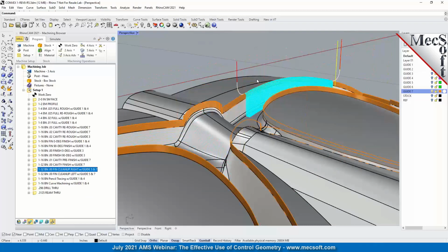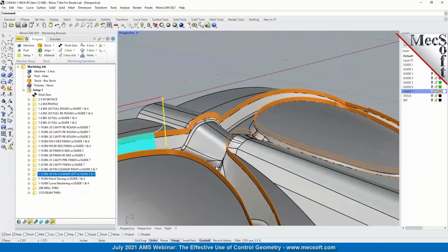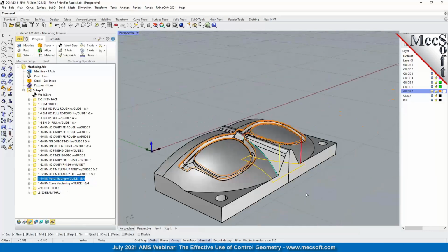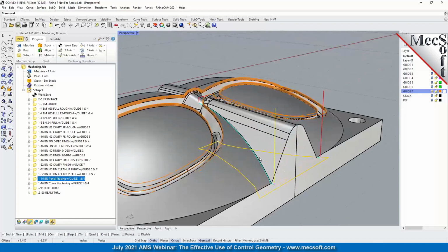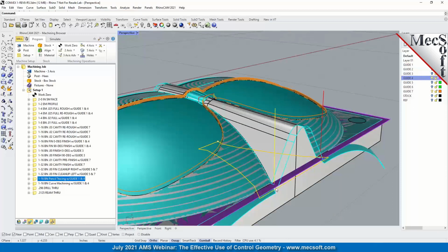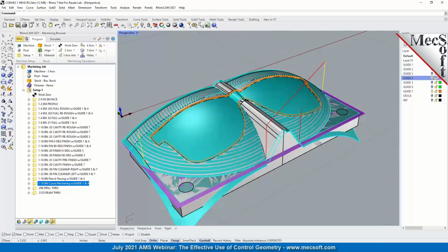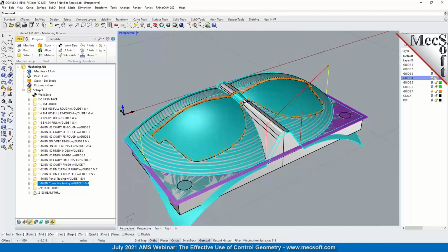And then move on past, we got extra cleanup there, extra cleanup here, and then extra pencil tracing to clean up this edge. And again, this is with 1 and 4 on. So it cleans up this edge right here using these perimeter curves and some additional curve machining. Let's see, turn 1 and 4 on. 1 and 4. Okay. Some additional curve machining here along these edges.